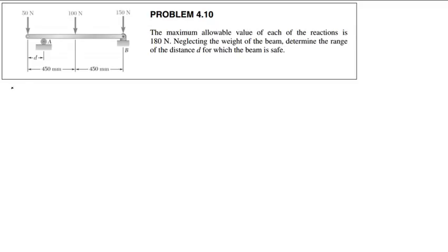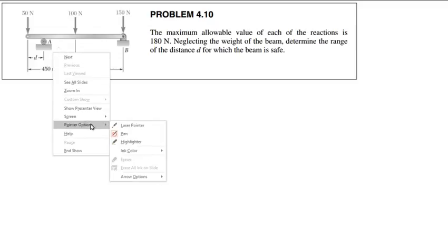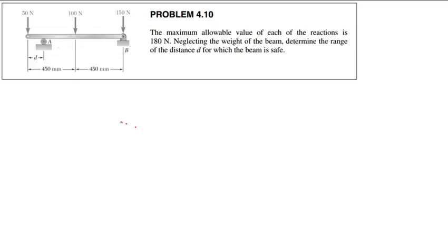So let's look here. We have a free body diagram. Let me modify this to make it a free body diagram. Let me show the x reaction here. I'm going to call these AY, BY, and BX. And these are our reactions. However, I know BX is going to be equal to 0 because there are no horizontal loads upon the structure.